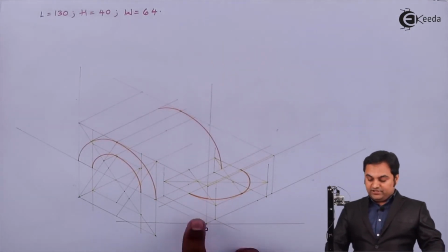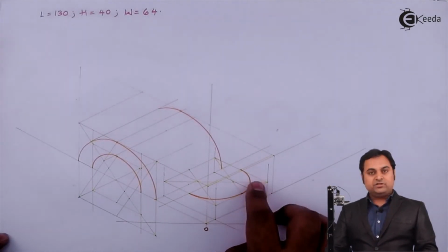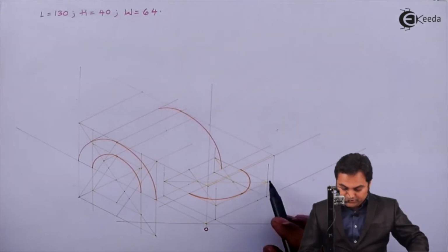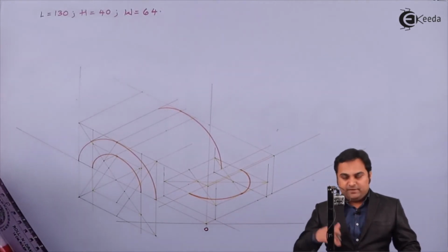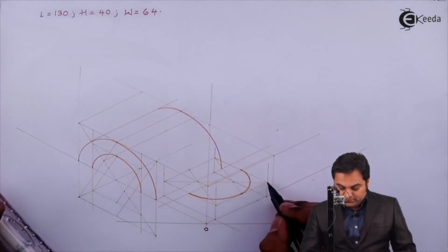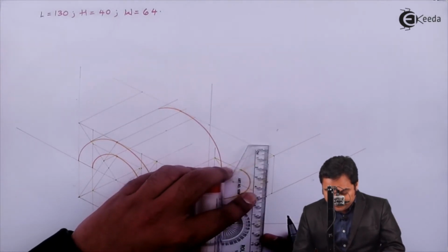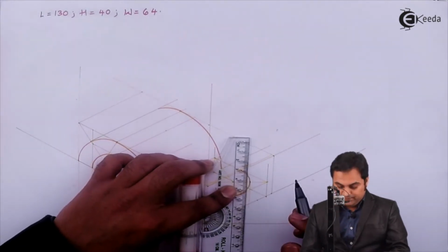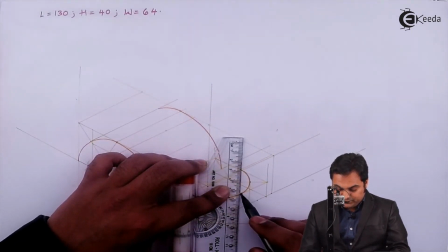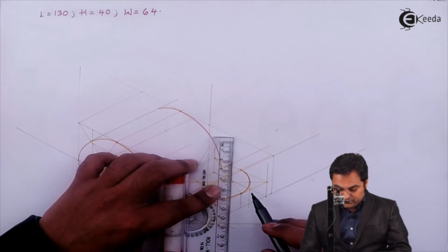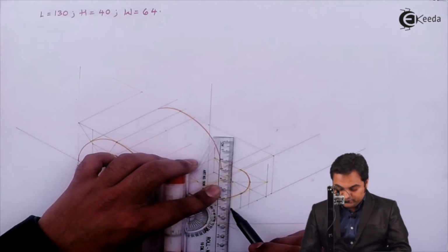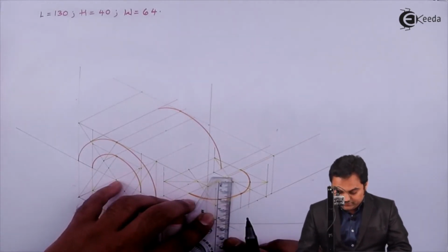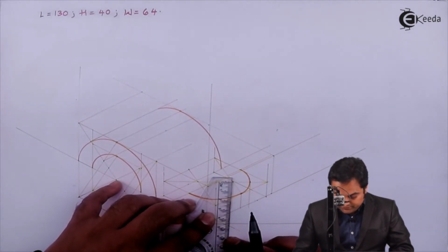A similar semicircle will be there at the bottom as well, because here this part is having a height of 15 mm. For that I'll be projecting its points 15 mm down, like where this arc is cutting the longer diagonal. First I'm projecting that point downwards, then where it is ending at this point, the midpoint is down. Next the center. So first I have projected these 3 points downwards. Now the center will shift down by 15 mm.